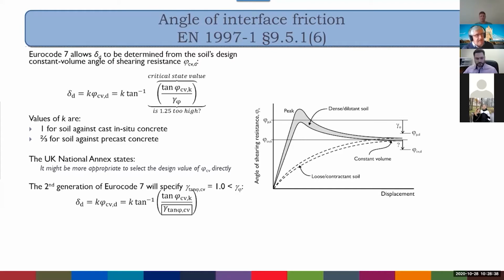Now, you don't see that in a regular shear box test or a regular triaxial test because the sample breaks after the peak. You have to do a particular type of test to measure that post-peak behavior. It's a similar problem with testing the strength of steel, which has a peak and then a post-peak behavior. Brittle materials.